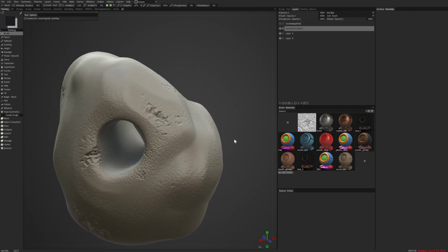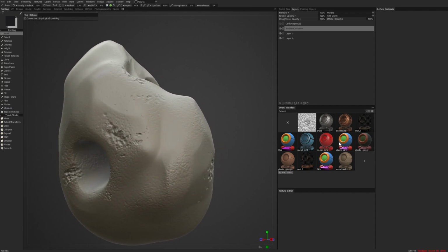We can do something like this in ZBrush using poly paint or vertex paint. It basically paints on the vertices, so the more dense your sculpt mesh is, you can paint on each vert and get really nice looking stuff. But to my understanding, at least last I've used it, it's not PBR based, so you can't get proper metalness, roughness, etc. Whereas in 3D Coat you can.